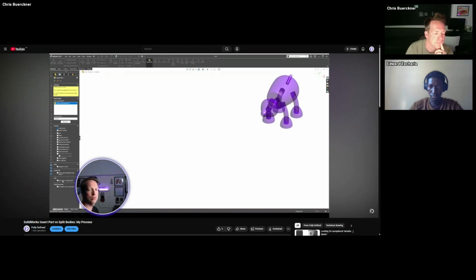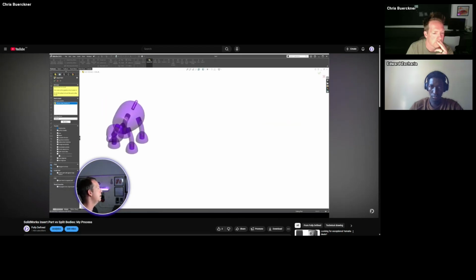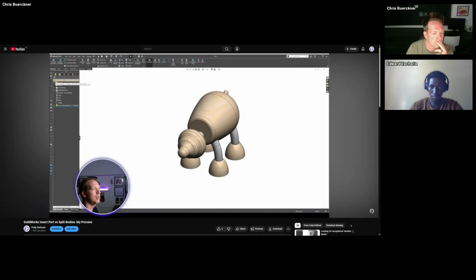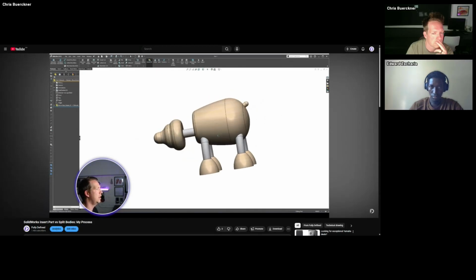That's something you would want to do if you never want to have it linked back to the original. Typically, I would suggest leaving that unchecked because you want to be able to path your way back to the master file. Different for everyone though. All right. And visual properties, you can propagate from the original part. Doesn't always work, but I'm going to tick that one here. So I'm going to press OK.